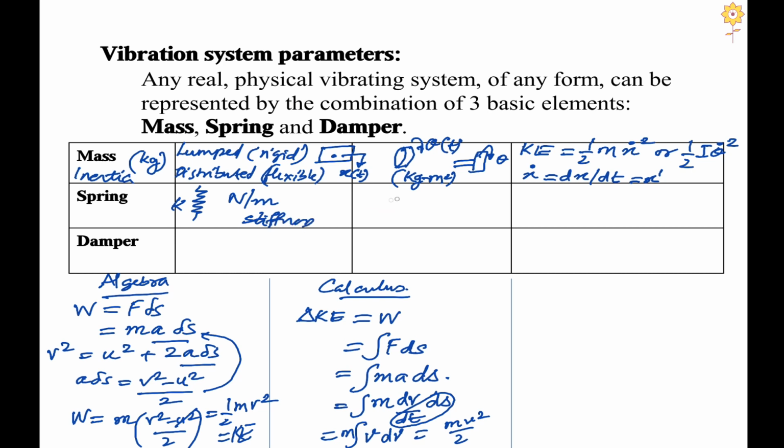Likewise, I can talk about the angular deformation. So in a real case I can have the spring given by a shaft which has the spring properties, and this is defined by the symbol K suffix T, that is torsional stiffness. So we can also denote the torsional spring, something of this kind. The unit for this is Newton meter per radian, that is, it is defined by the torque required for causing unit angular deformation, and the unit of angular deformation in SI units is radians.